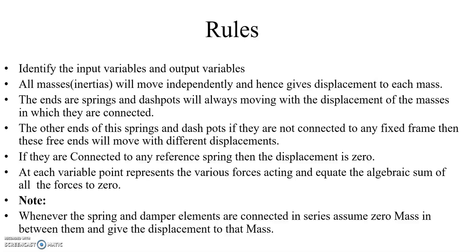The other ends of the springs and dampers, if they are not connected to any fixed frame, will move with different displacements. If they are connected to a fixed reference frame, then the displacement is zero. At each variable point, represent the various forces acting and equate the algebraic sum of all the forces to zero.